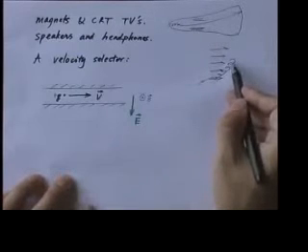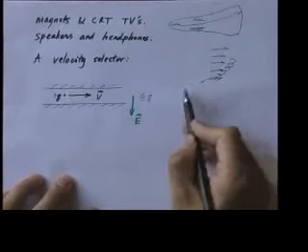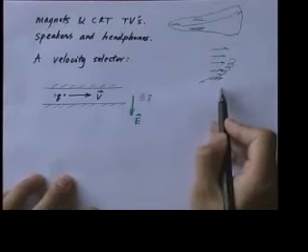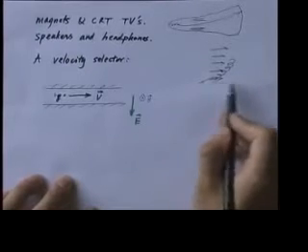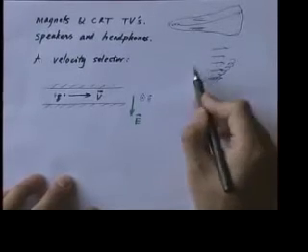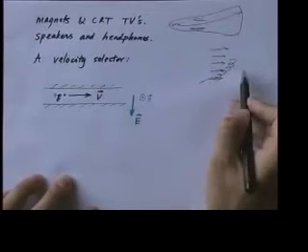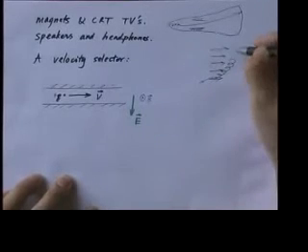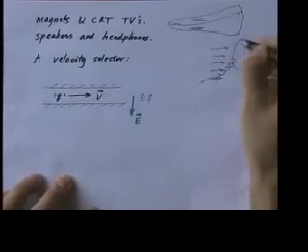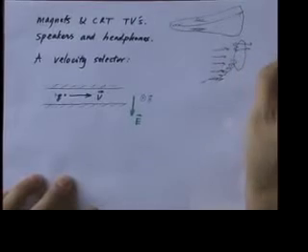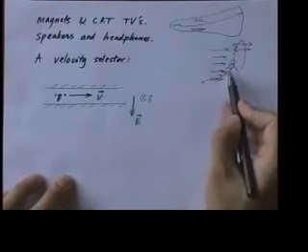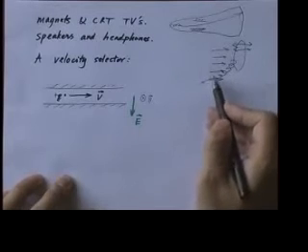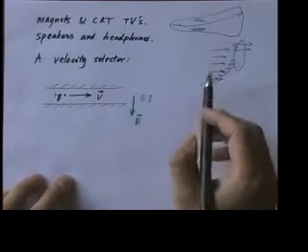So for example, if you have an oscillatory motion, say a sound source turned into an electrical signal, the current will go back and forth, back and forth, and that causes a variable force going back and forth, exerted on the coil. And the coil is attached to what's called a diaphragm. This diaphragm therefore is going to oscillate back and forth, and the oscillation is totally in response to the magnetic force, which in turn is proportional to the current, which in turn is proportional to the signal that drives it.